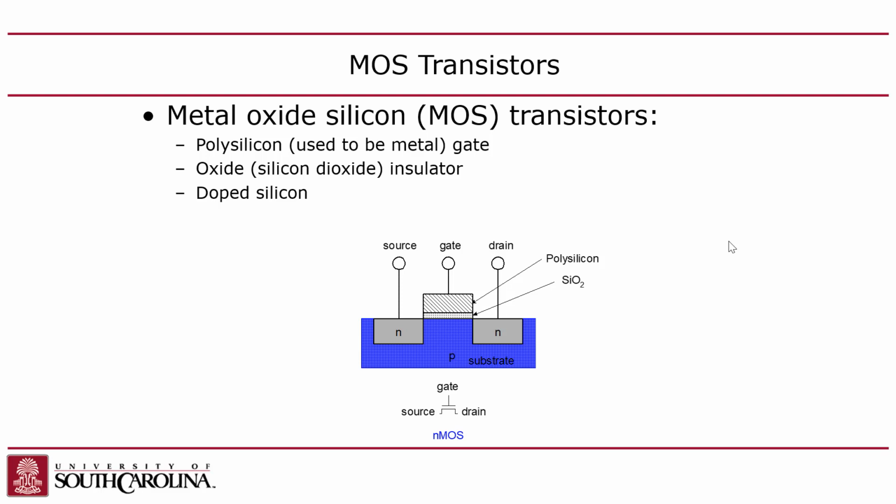You might have heard that term, photolithography. So the way this works is that you apply a mask over the top of this thing, and there's little windows in that mask where those diffusion areas are. So when you hit it with the arsenic gas, that arsenic gas diffuses into the areas that are not covered by the mask, right? So this is all done through a masking process. So basically you protect everything but the n-type diffusion areas, and then you create arsenic vapor, which again,